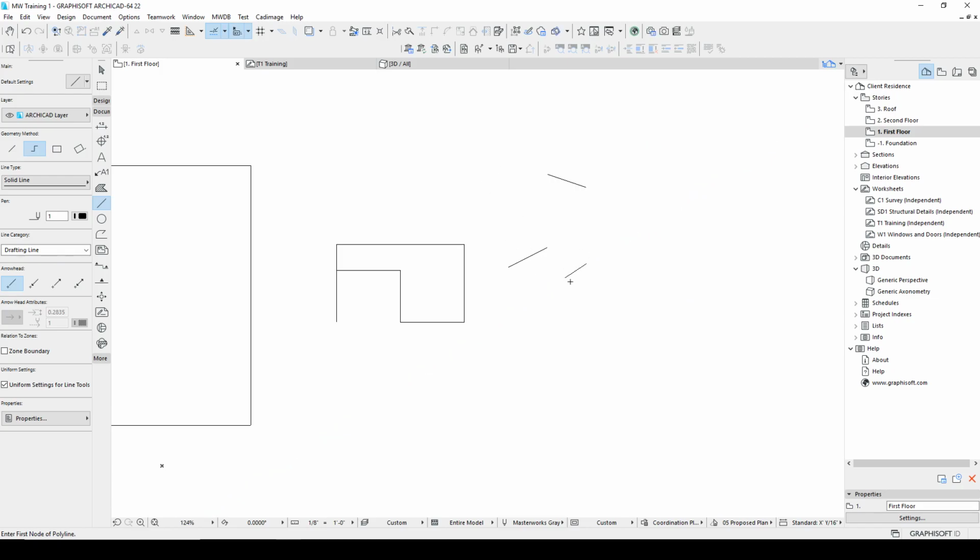Now I'm going to show you the measure tool, which is M, or come up here, but don't do that. It's too slow. Hit M, select this point, and you'll see, yes, that is in fact exactly 4 feet. Notice the decimal zeros. You're going to have to set the precision up. If you're using this strategy with the decimal inches, make sure you use the 3 decimal places and 4 decimal places for the angle.